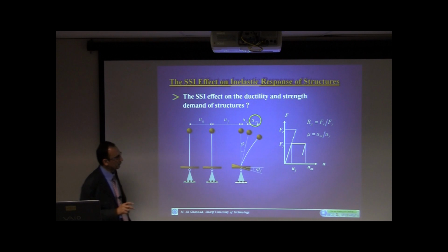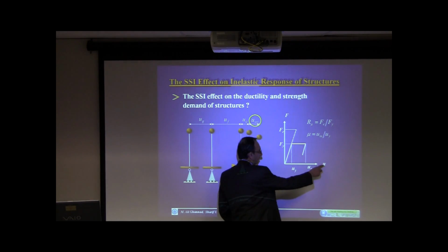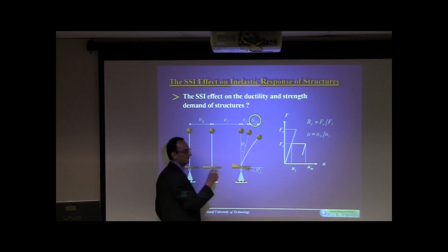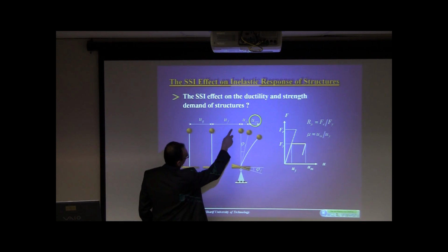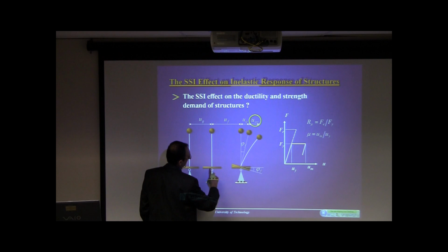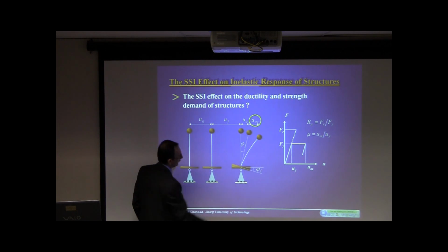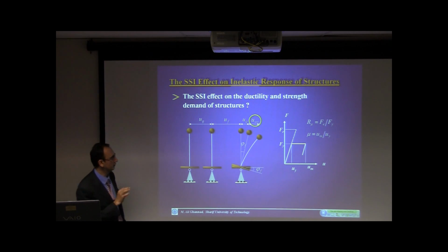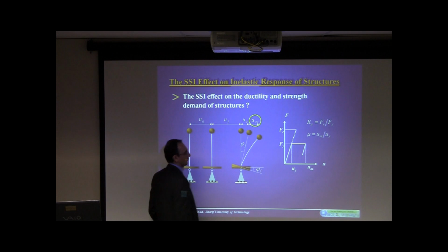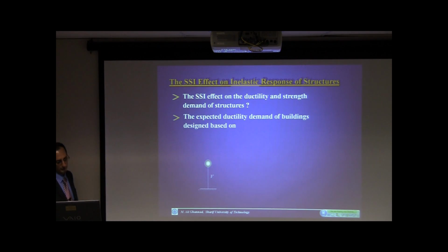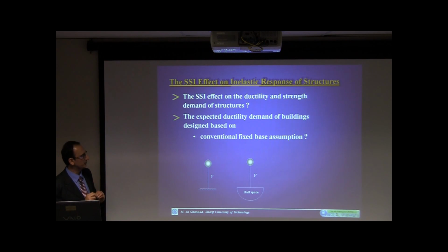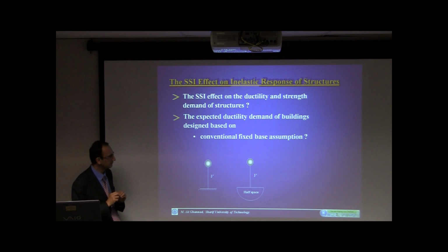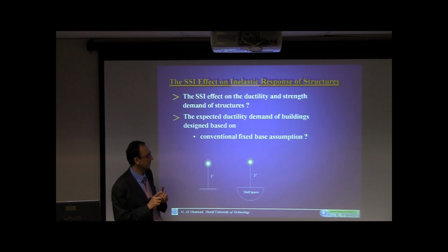And of course, when we say U, we mean the displacement in the structure itself, because we are ground free. The displacement of foundation, displacement due to rotation of the structure, but we are going to monitor the displacement inside the structure, of course. And after that, we are going to answer the question: the expected ductility demand for buildings designed based on conventional fixed base assumption.